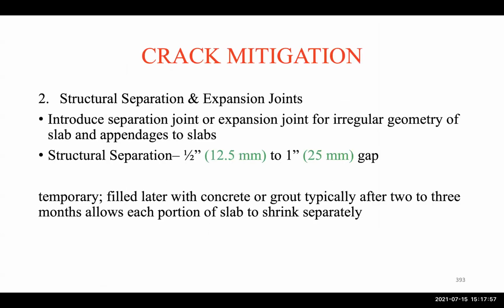Here we don't have, we have the walls and that's it. Here you have columns in between also. So it's restrained in both ways, and it covers maybe half or more than half of the floor area. So that's also unfavorable. That's the layout and the planning of the floors. So that will help in crack mitigation.